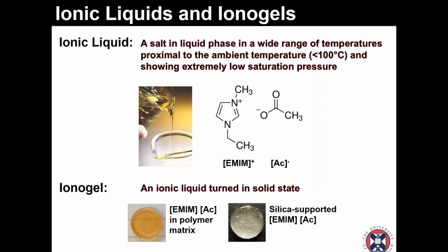Now, the capability of ionic liquids, and accordingly ionogels, to retain water is very well known, and usually this is an unwanted behavior, because the majority of research on sorption on ionic liquids focuses on CO2 capture and utilization in supercapacitors, where the water is unwanted because it is going to reduce the performance of the technology.